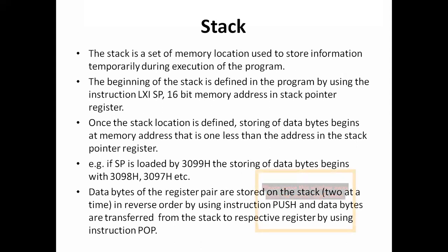So that is why whenever we want to use a certain memory area in the form of a stack, the top of the memory is used, because whenever we put the top of the memory into the stack pointer, below that memory, we are able to store the data. So that is why the address which is stored in the stack pointer is known as the stack top address.